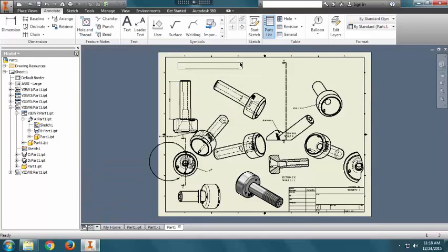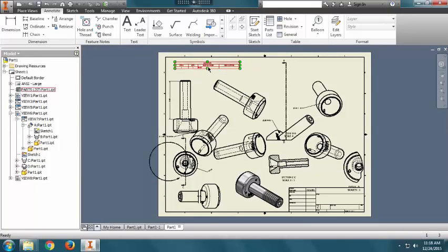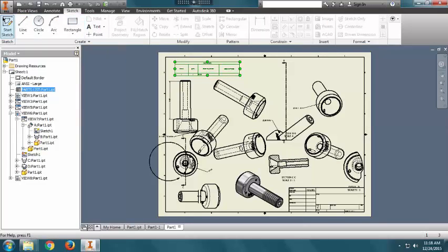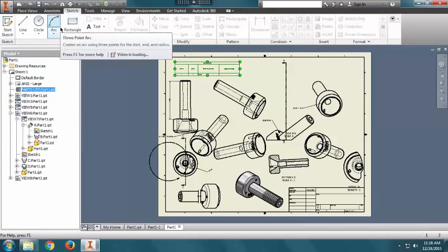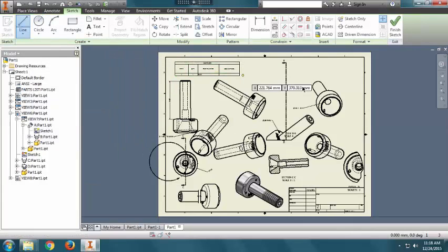So you can create a box here. So this box can be enlarged, and this is called the part list. So you can mention which parts you have used in this assembly. This is not an assembly again, so we don't have a lot of parts, this is only a single part, so we don't have any option. But if you have an assembly, you can mention all the parts over here. So these are the tools that we have in solid component design that are reflected here. If you want to make some drawing here to indicate your preferences, you can draw that too.